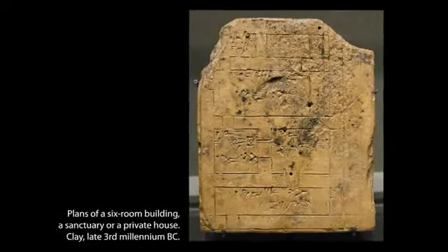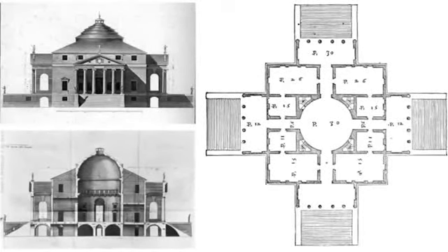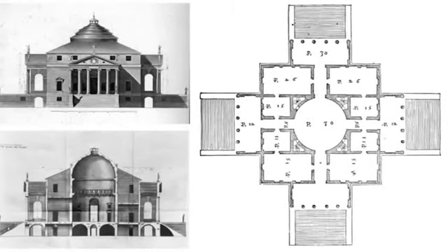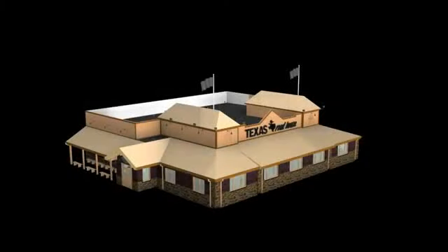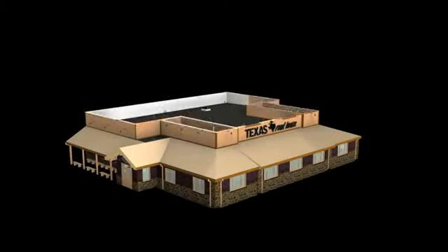They used the triadic system to design these great works of faith. The triadic system utilizes plans, sections, and elevations to describe a building from specific viewpoints. A plan is essentially what you would see if you cut through the building 3 feet above the floor and looked directly downward.